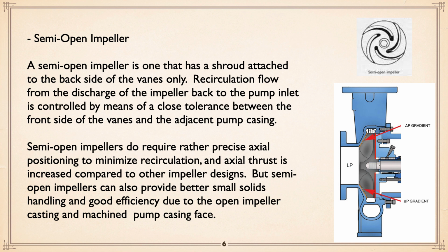There's a couple of things about semi-open impellers. They're great for handling small solids because of the action of the casing relative to the inside of the impeller. And they do have good efficiency as a general rule, because the impeller can be cast and machined fairly easily.